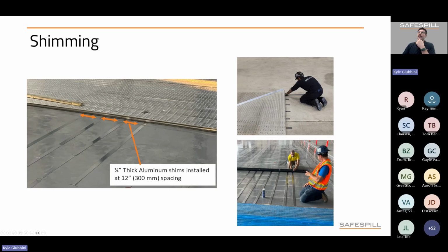And finally, a common thing that comes up with retrofits is that the slab may have shifted over time. We always want to make sure that we're meeting the required slope for these hangars with at least a 0.5% slope. And so in order to do that, we don't necessarily modify the concrete, but rather we utilize a shimming method just to elevate and slope the floor profiles during installation. So here's a couple of examples of the shimming process that we used for that floor.